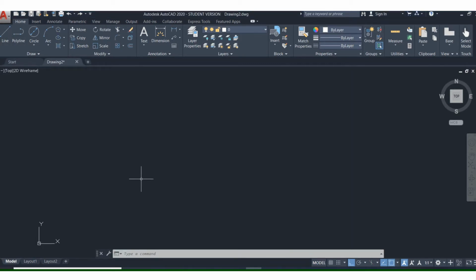The best way I found to draw with line is click a point, and remember you can start anywhere you want, and then move your cursor whatever direction you want to go. For example, right, left, up, down. Now with my ortho mode on, I'm restricted, remember. So if I wanted to draw a rectangle, for example, I would move my cursor to the right, but don't click the mouse, and then type in the distance. So with my keyboard, 8, and hit enter to finish it.